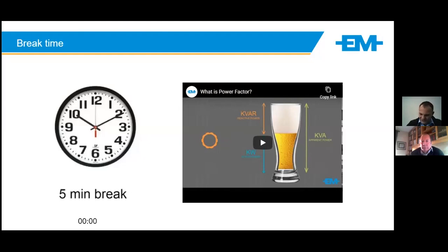Almost every single system, or a high percentage of systems now, all require the reactors. This is due to the nature of the loads. Everyone's gone to LED lighting, to variable speed drives, to multiple different non-linear AC to DC conversion systems on the load to save power. But in doing this, the power quality is being reduced. This poorer power quality is then seen by the LV grid, and then also the capacitor system.